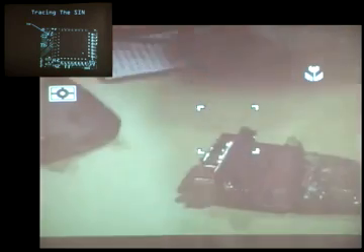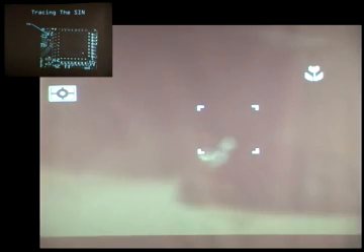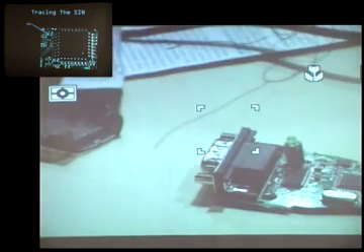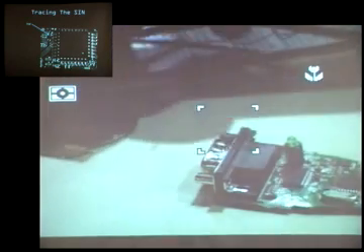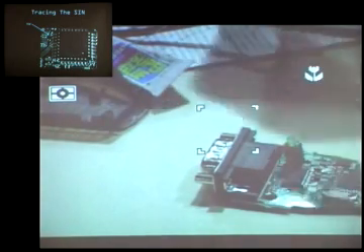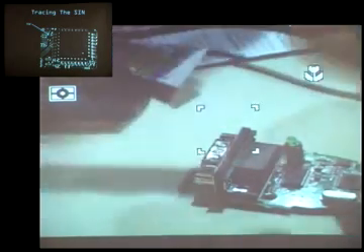Now I really want to solder on some signals to this microcontroller over here. And so I've got my soldering iron, I've got my wire, I've got my solder. Give me 1 second here. And I'm covering with the shadow so you can't see anything. All right, so what I need to do is I'm going to take a piece of wire here, and I'm going to cut off just a little piece that I'm going to eventually tack around this thing, off the length so I can actually hook up with something else.